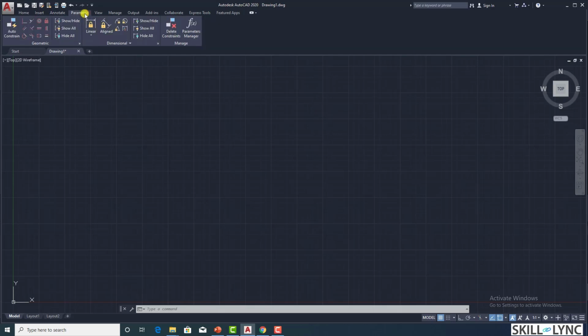In the Parametric tooling, we'll look into this in the later part of the course. This is kind of a customizable drawing that you can draw. You give an input dimension not as an absolute value but as a relative value. That is, you name it as X or correlate with another one. That is, line A is 3 times that of line B. So when you're scaling line A, line B gets scaled automatically. So this is what is meant by parameterization, or again constraining.